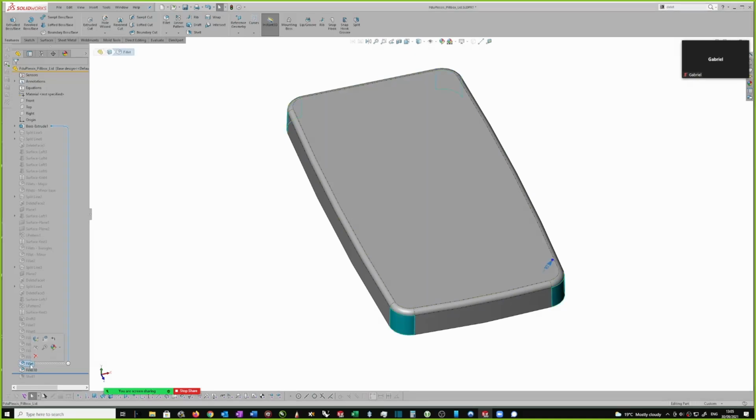If you click on the feature that you're looking at, and you click again and pull away slightly, you can rename it. So I'm going to call this major, what would this be? First config. Just because I've got lots of major fillets, I'm going to do the same with this second one. The reason I'm going through configurations is because you can start with the basic shape, and then fill in different features, and quickly see which one you like. And you can present them as well.